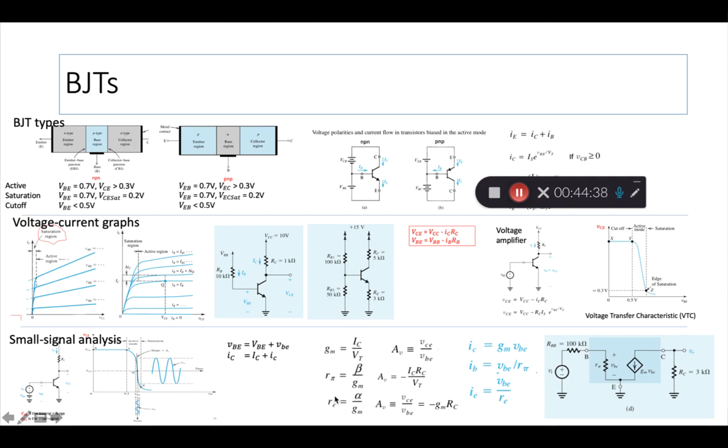Here are two more resistors which are used in the small signal model, right? r_pi is this resistance. This is the resistance looking into the base-emitter circuit, that's called r_pi, and then r_e is looking also into the input circuit, but looking from the emitter side.